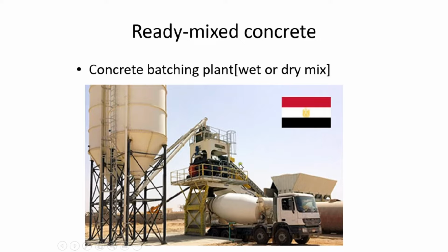It's mixed for a certain period, and the water is also poured so that the mixture is complete. Then it's discharged into a ready mixed truck. I'm talking about the wet mixture. If it's a dry mixture, you don't use water at the plant, you just add water when the ready mix truck reaches the site.